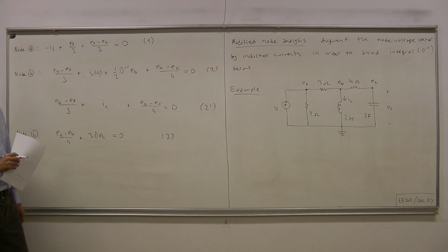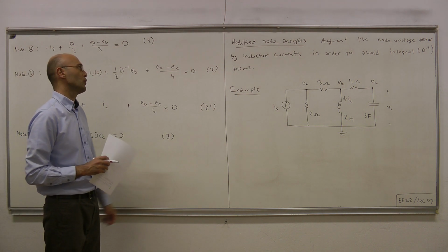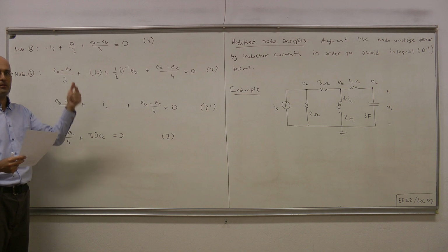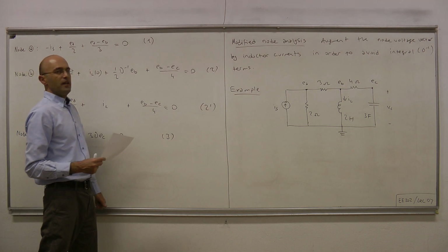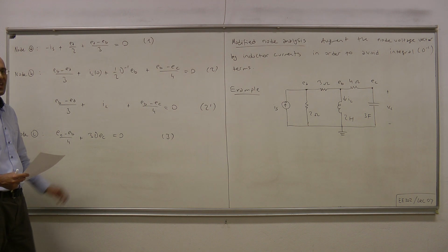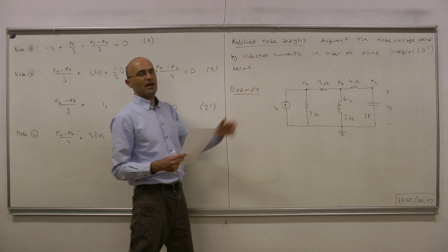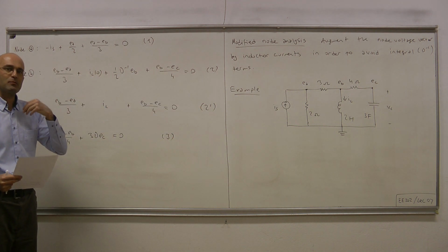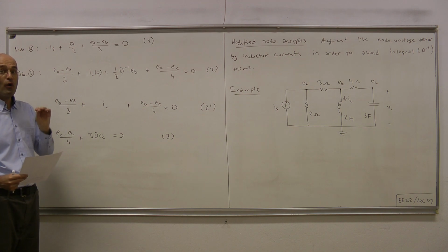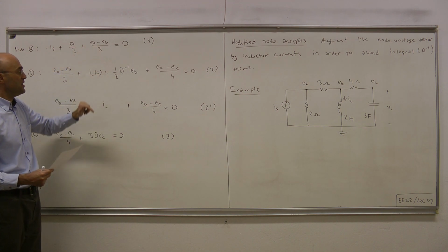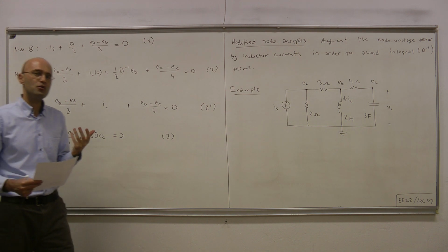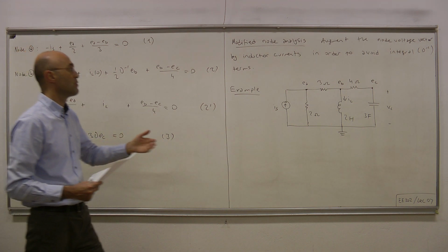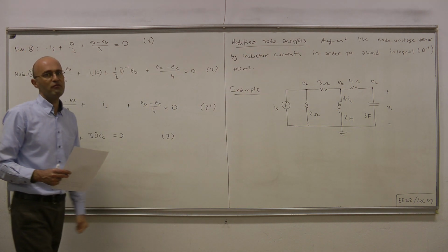Okay. Now we have all the equations that we need for the standard node analysis, namely equation 1, 2, and 3. And all the equations are in terms of the formulation variables, the initial conditions, and the input. But if we go with the modified node analysis, we have 1, we have 2 prime, we have 3. So we have 3 equations, but the problem with that is we have now 4 unknowns, namely EA, EB, EC, and also IL. Since we have 4 unknowns or 4 formulation variables, what we require is a 4th equation if you want to formulate using modified node analysis.